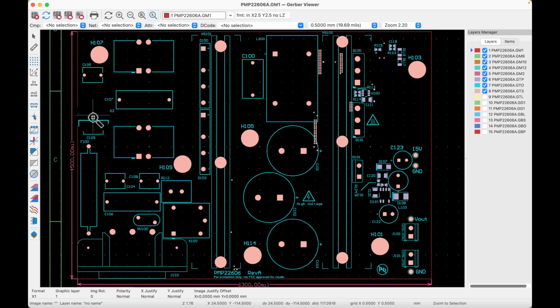I could move this L over there a little bit, get closer to this guy because I got a C and an L right next to this guy. So I could move around my reference designators. And you know how I was talking about how you should be able to read these all one direction, so I can flip these guys around. So I can make some changes on this board. See, some of these guys are upside down because they're just put on sloppy.